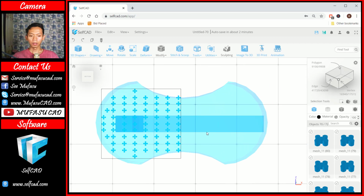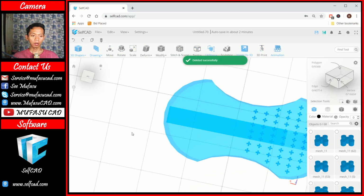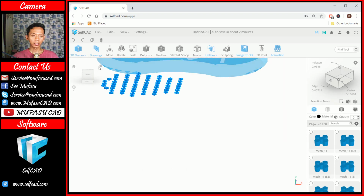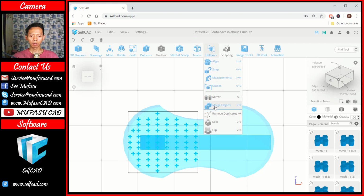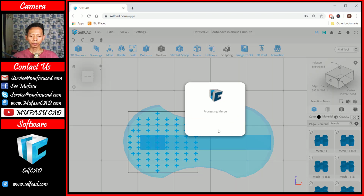We can combine into one by using this merge objects option, but first we need to delete these 2 objects. Okay, you can select these 4 objects, and you can delete. Yes, next you can select all these objects. Okay, change again to bottom view. Select all these objects, and then we can use merge objects to combine into one.